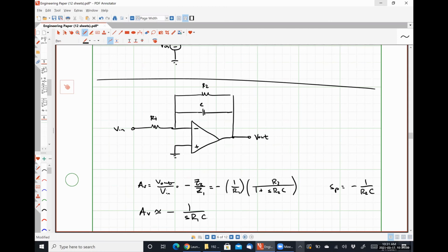So I don't know, it tickles me to finally come full circle because I can remember giving you guys a design problem in circuits 2 where I asked you to make a multi-stage op amp where you had to convert a sinusoidal signal into a cosine signal or vice versa, and everybody that tried to do it with an integrator always saw that their output went towards one of the supply rails. And so I was like, you either need to put a resistor in or use a differentiator, and we have fully explained why a year and a half later. So wonderful.